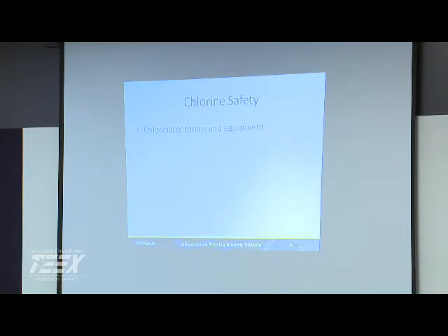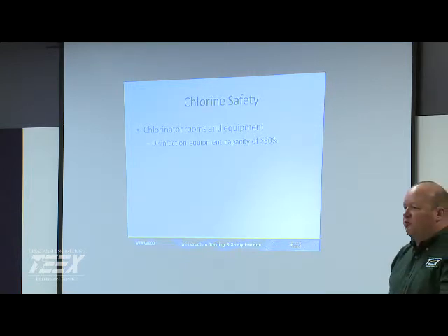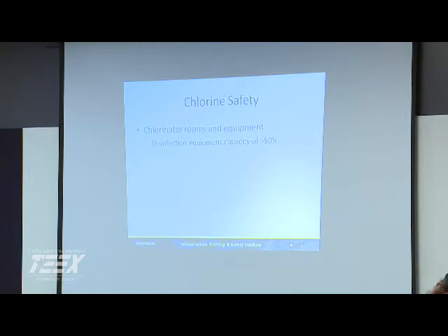So look at safety. Obviously, we need to make sure we keep our equipment separated. We need to keep it up to date. If you're putting on valves and all that, use new washers. Are y'all using lead washers? Yeah, you need to have some way to recycle those, but always put on a new one. Using old ones is going to cause you a lot of problems. Start talking about redundancy in our system and capacity. We have to have 50% capacity over what would be expected under peak demand and peak flow. We have 50% above that.